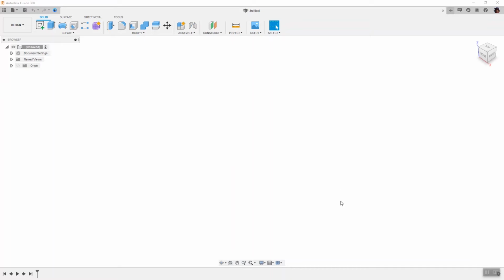Before we even begin, let's look at a few settings. And one of them down here is at grids and snaps. There is a whole video I've created on my preferred settings for Fusion, but we can skip that for now. And the most important thing is I want you to turn off the snap to grid, and I want you to turn off the incremental move.